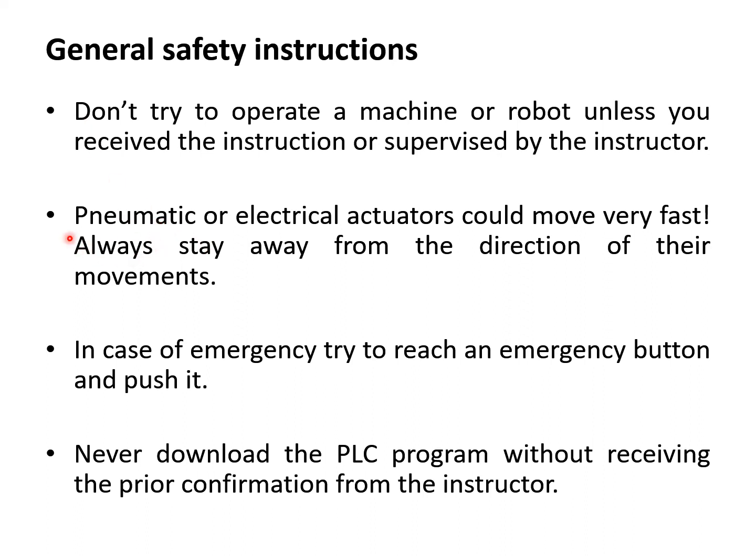Pneumatic parts and hydraulic parts are very powerful and move very fast. So always stay away from those, specifically if you don't have knowledge and didn't get the instruction. In case of emergency, try to reach an emergency button and push it. Never download the PLC program without receiving prior confirmation from the instructor.